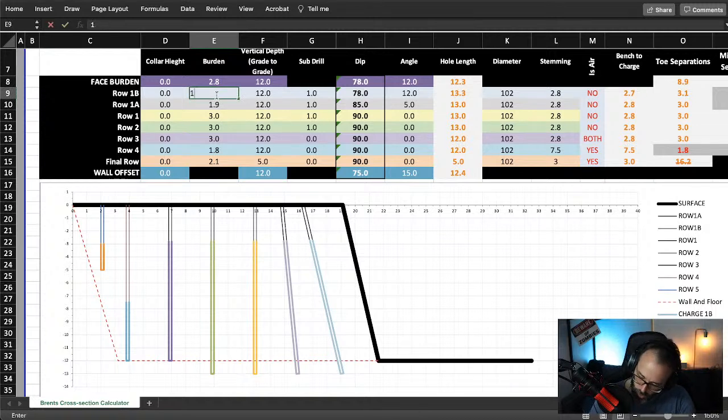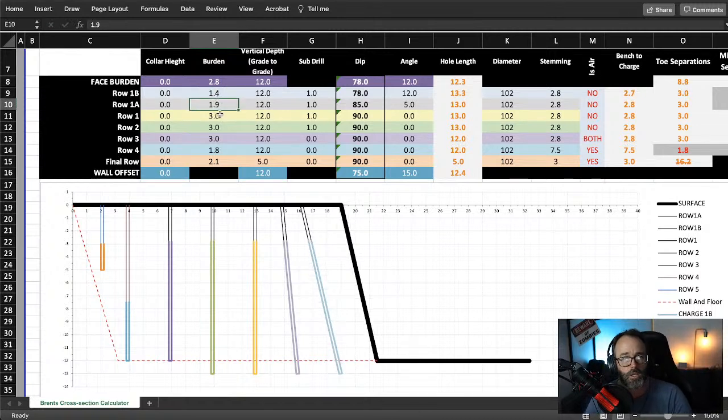So we set at 1.4 behind a 12 degree hole, and because we're going to do a staggered blast, we've got the 2 holes there, and then this next one's going to be in the middle. So we need to think about this hole at 12 and this hole at, well, it might be at 17. Then we need to split the difference between those two.